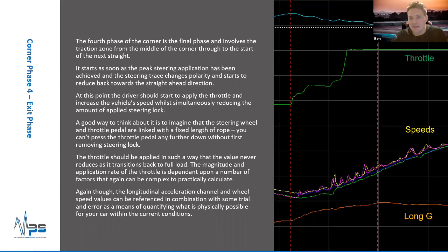And all that's happened there is the car's still trying to turn, the front corners are still trying to create a slip angle and get some cornering grip, and then all of a sudden, as soon as you pick the throttle up, the car will naturally squat, transfer the load to the rear, and now the tyres which hadn't finished cornering in the first place have now got less load on them, they've got less available grip, and the understeer just builds.